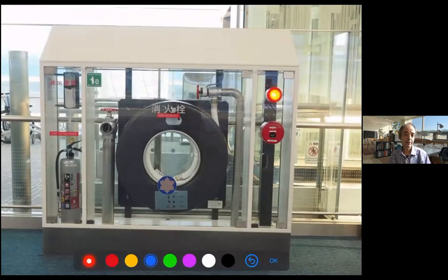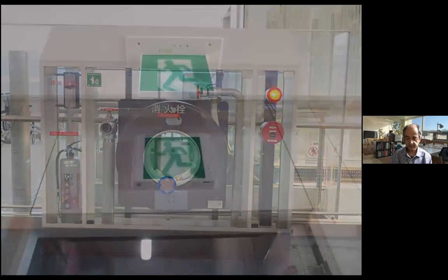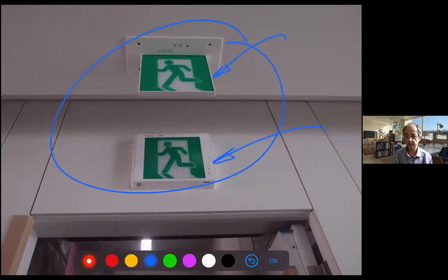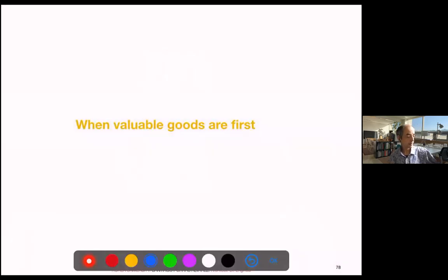This is a nice design. This is Haneda Airport in Tokyo. Nice design. And this is the signage. Signage is extremely important. It's very frustrating because you may design carefully the signage and the inspector will tell you to do it in the usual way. Be careful with the redundancy because it may be confusing, and be very clear so people are not lost when they leave the building.